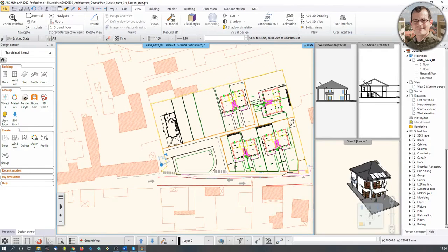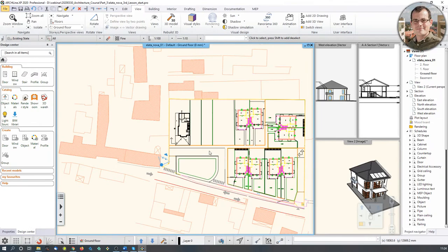Let's see what happens if I use this hotkey. Ctrl-Shift-R toggles the floor plan back and forth. So that way you can have multiple views of the same floor plan, actually. And if you want to make it more convenient to work on, then that's how you can do that. So, very important distinction: Project North can be arbitrary, and True North is the one which actually influences your geolocation and shadows.